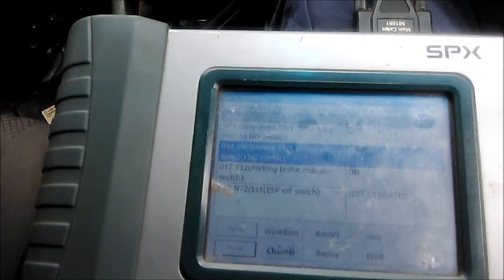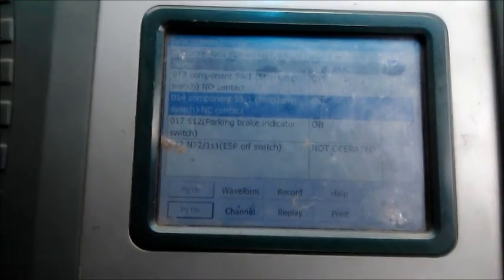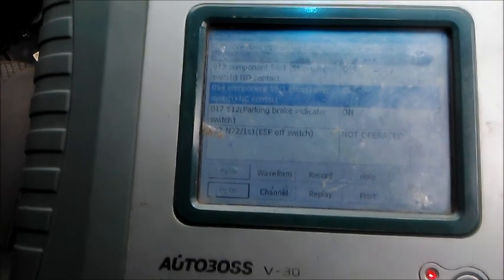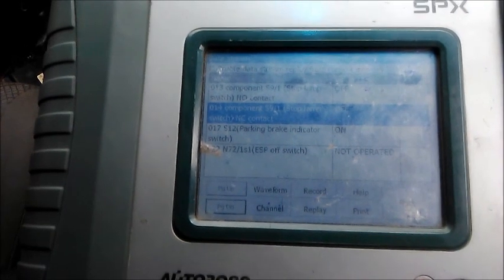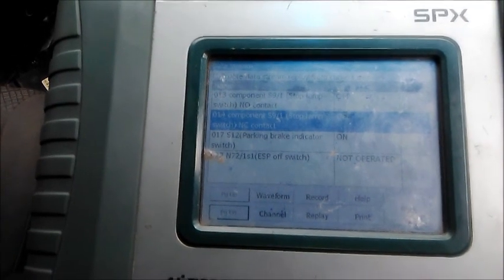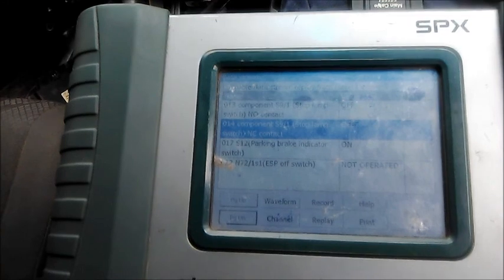So that's where I'm going. We certainly need to change, or at least after verifying that brake switch in the MFU, not its wires, we need to change that switch. Your code again. But now I need to do a test drive of verifying a complaint.